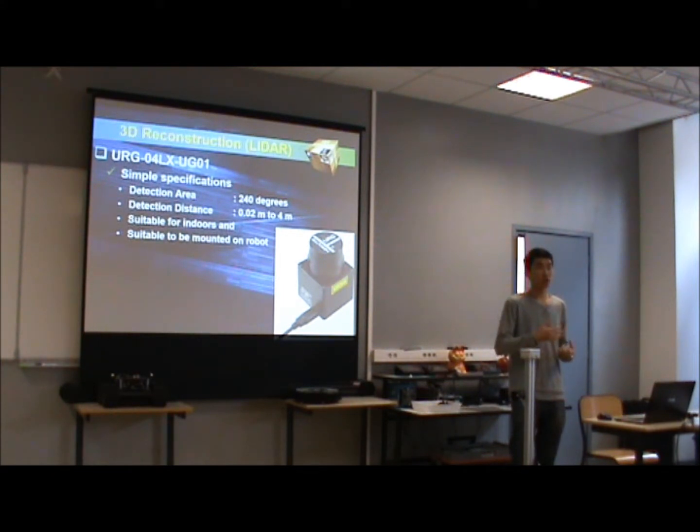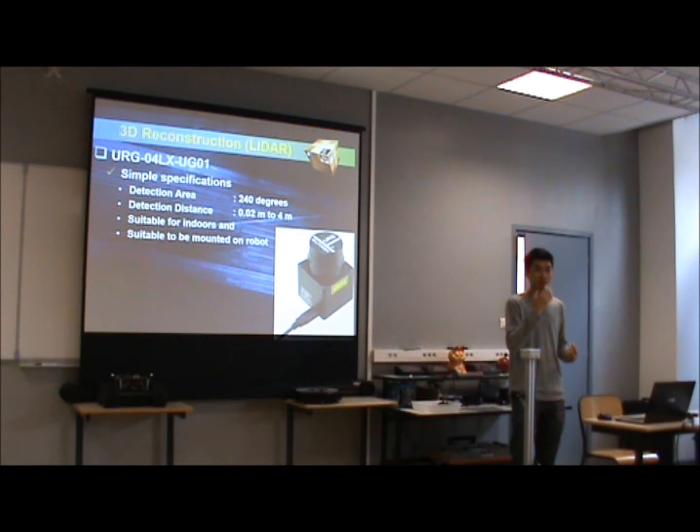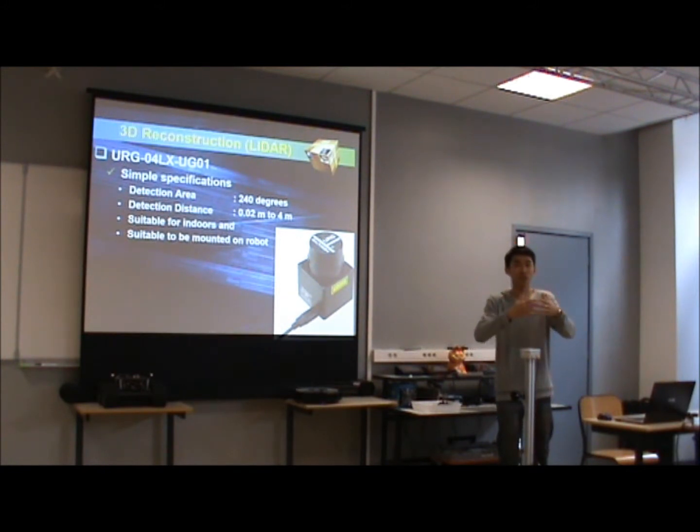Through online research, the most popular mapping that doesn't require a robot or odometry is Hector mapping. I tried Hector mapping, but in the end it failed in the sense that I managed to open it and visualize it. It can run in RViz, but the map couldn't be produced. The map produced is something like overlapping points that doesn't really record the real map of the scene. If you move the sensor a bit, the map will be distorted wholly. You cannot actually have an accurate map.